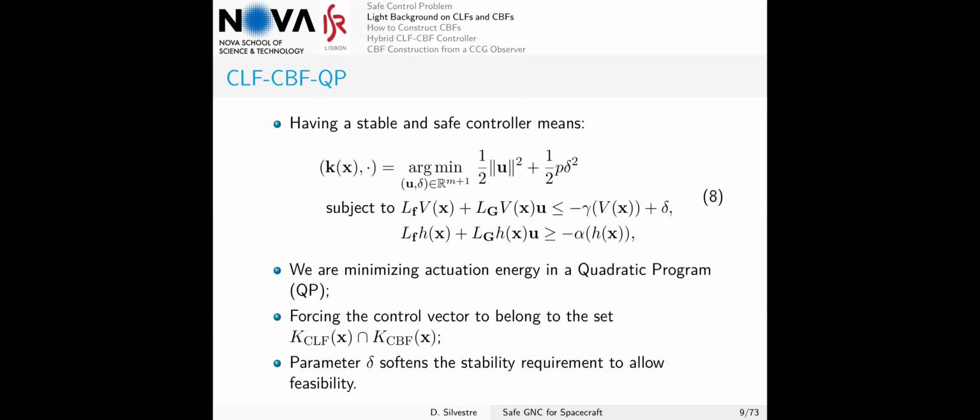So I would say here that we are disregarding the nominal controller, but if the original dynamics is in strict feedback form and has relative degree higher than 1, in the end we will do backstepping, and in the backstepping approach, the first part is to design some nominal controller that pre-stabilizes the upper level. And so in the end, you still have a nominal controller. It's just that you don't have a nominal controller for the whole thing. Might offer us a little bit of flexibility.